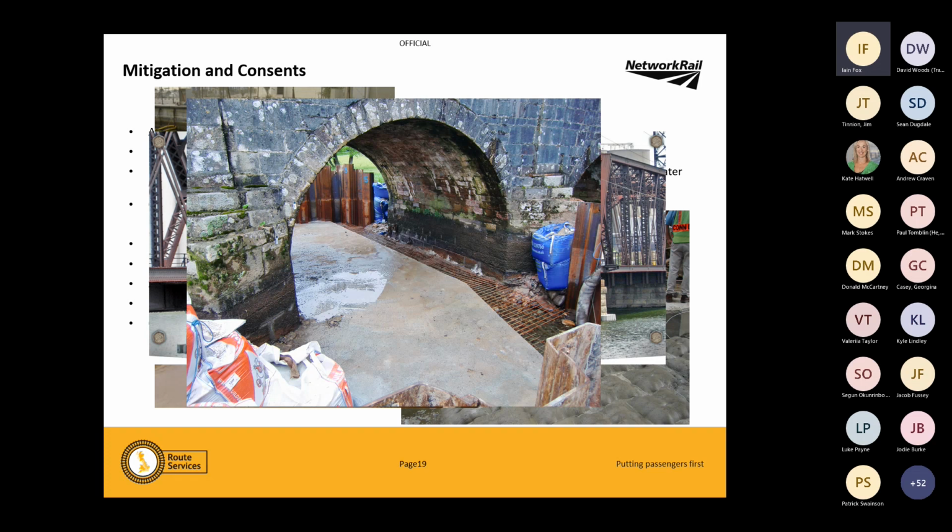So, some mitigation: rock armour, we've all seen that around. It varies in size from tennis ball size up to VW Beetle car size if you're on an estuary or a tidal lagoon. We can get these rock rolls, which are like gabion baskets. Just don't, they're terrible. Concrete mattresses, these are quite popular. These are a geotextile that's zipped into shape around the structure, and then a concrete pump truck is parked somewhere near and it's filled with concrete. Concrete hardens, goes off, and you've effectively got a concrete invert.